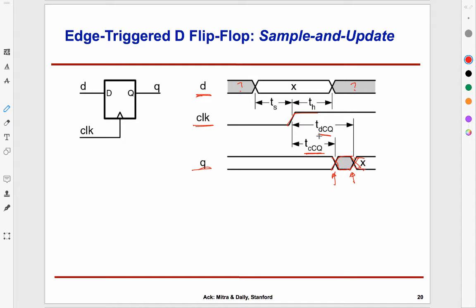So what does that mean? If we look at flip-flops in their most native form, deep at the circuit level, what they're really doing is sampling a signal, right? When the clock comes, they observe the input, and whatever that input is, I'm going to copy it into the output and of course remember it. Now, think about how you might do something like this. I'm trying to observe a signal, but if the signal itself is changing, my task would be pretty hard, right? I could capture it in the midst of it changing.